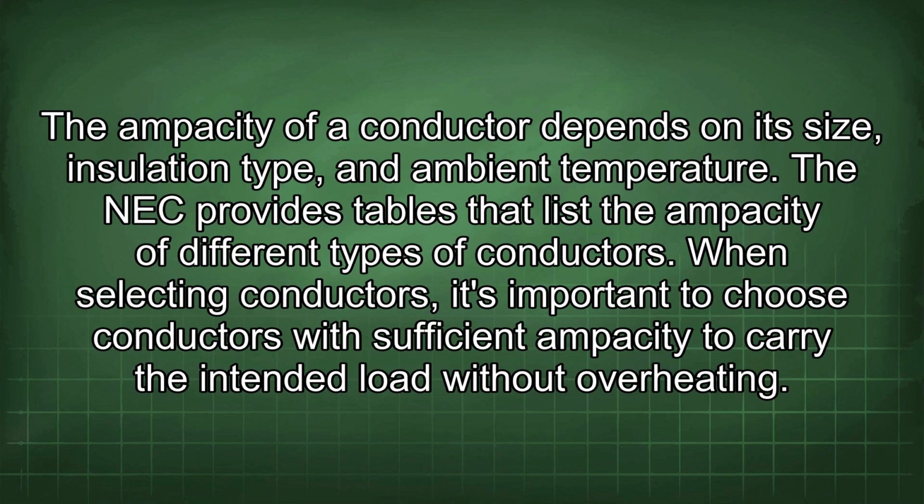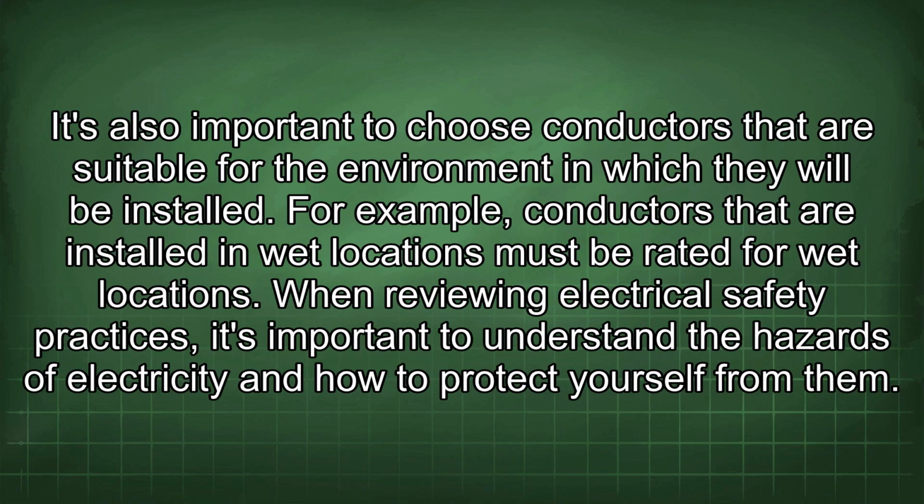When selecting conductors, it's important to choose conductors with sufficient ampacity to carry the intended load without overheating. It's also important to choose conductors that are suitable for the environment in which they will be installed. For example, conductors that are installed in wet locations must be rated for wet locations.